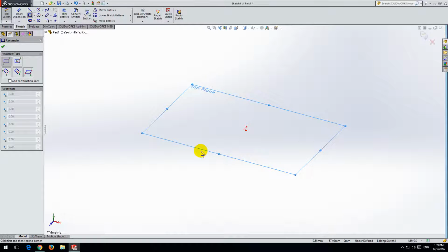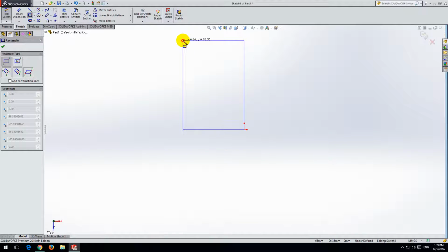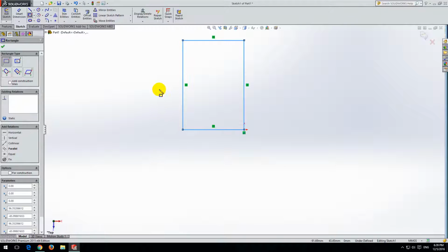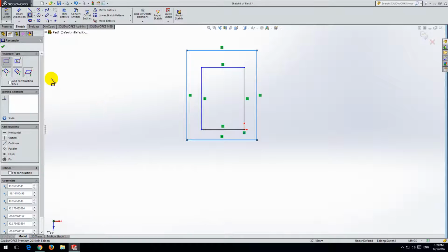Okay, now press the spacebar, and now click on this icon. Okay, now let's draw inside. So left click into the center and just drag up and release the left click. Okay, and let's draw another one outside, something like that. Accept it with this green OK sign.